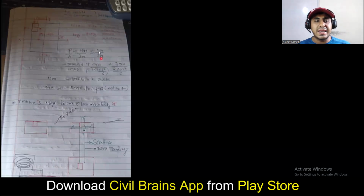So when you do all the calculation like this, again you see the maximum pressure is coming 876 kilonewton per square meter, which is greater than your SBC, and your minimum pressure is minus 554, which is less than 0. Again, both of these are not safe.